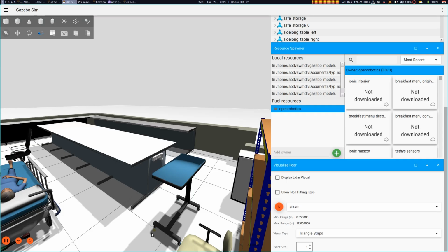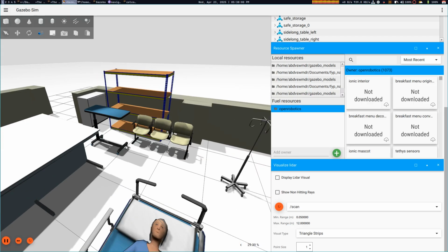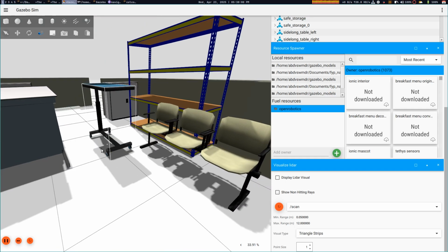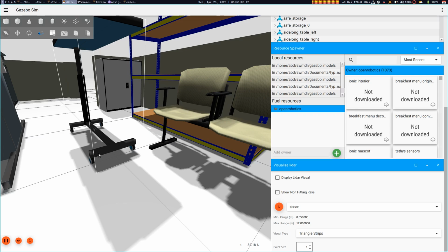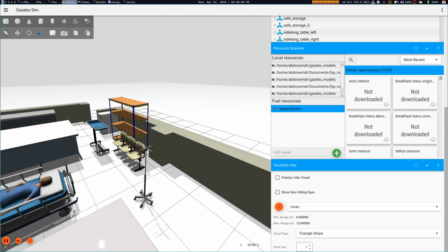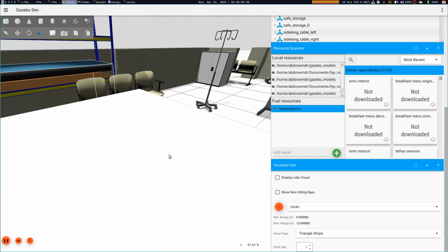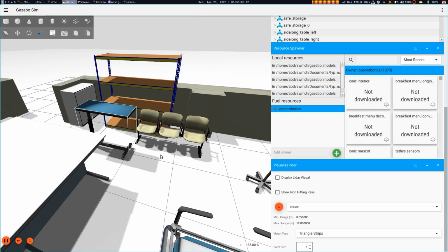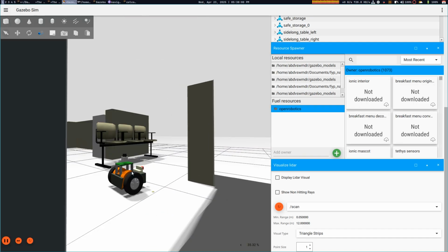It would just overrun it. So I'm not sure if maybe it's the way this obstacle was made, or it's because of the height of the base, because that's the one problem we have right now. It's the height. It cannot detect the very low obstacles, but that's because we're using one LiDAR, which is up here,